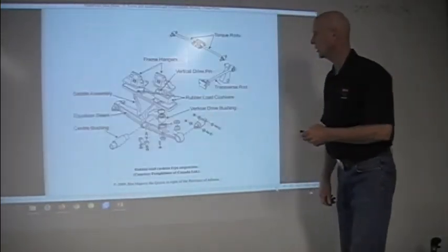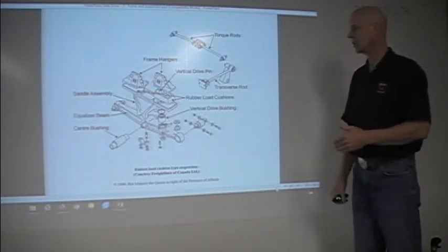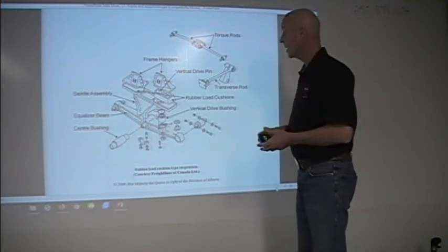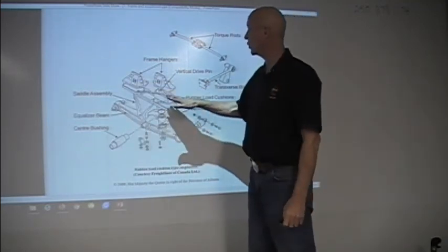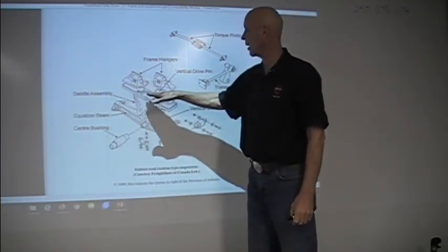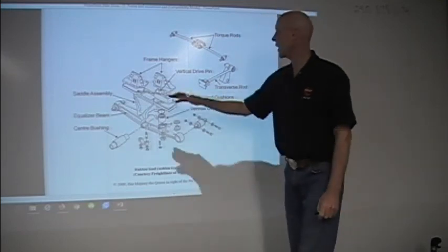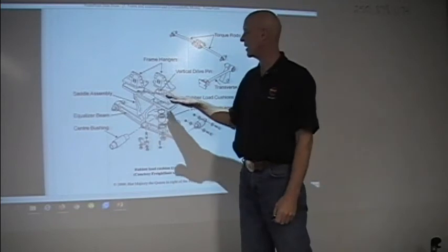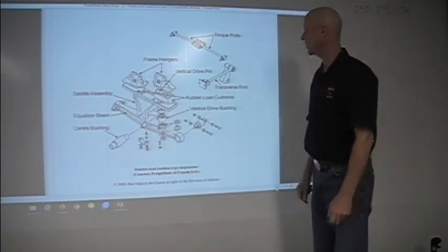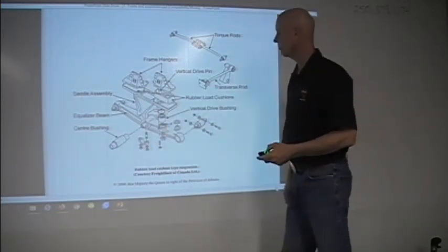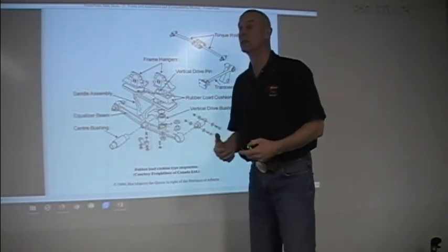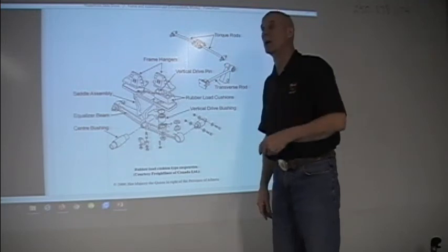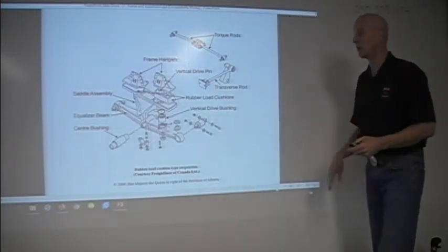What else? Now, when we're taking a look at rubber block with I-beams or walking beams, some of these will have 2 rubber blocks, some will have one in the center. If there is a round one in the center, that is your overload spring. If it doesn't have it, then there's no overload. This is a Hendrickson suspension. They are a tough suspension, but you can get one of these stuck on a pavement if it's out of alignment a bit.